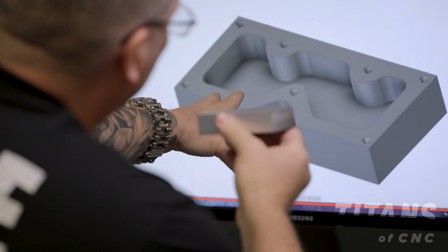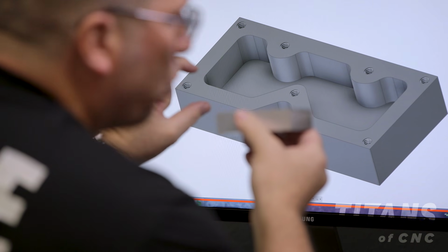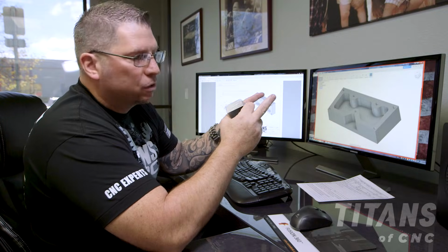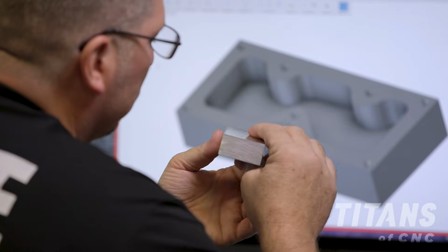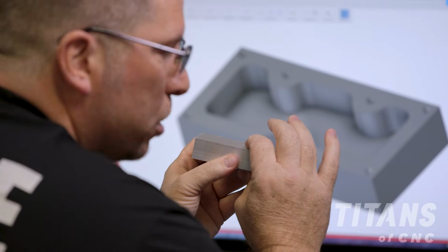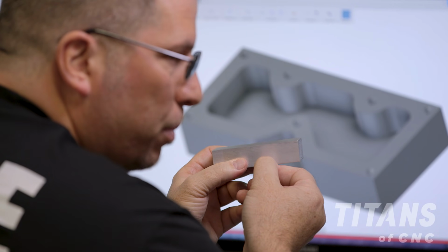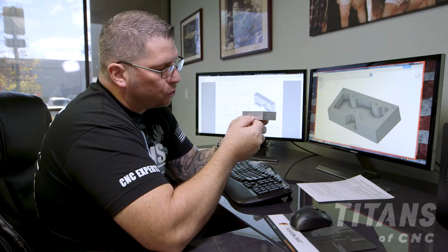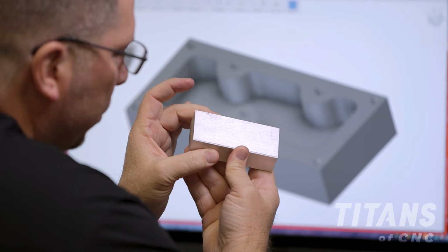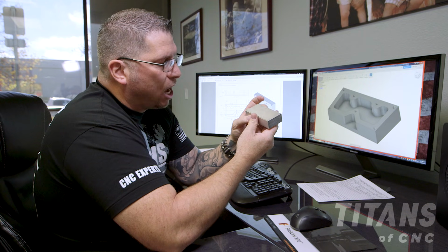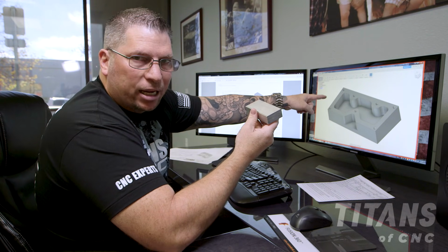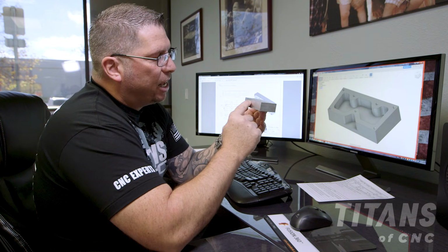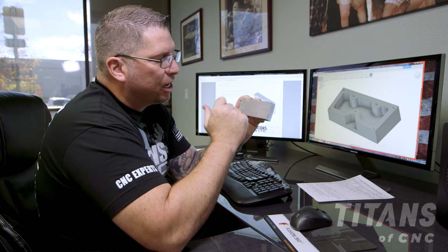We have a finished part that we drew up at 3/4 of an inch by 1.9 by 4 inches. Our finished stock that we called out is 1 inch, so that means there's a 1/4 inch at the bottom because the part is only 3/4 of an inch. Then the stock is the standard rectangle bar. It's 2 inches wide. The part is 1.9, so that's a difference of 100 thousandths. We're going to divide that in half, so we have an excess of 50 thousandths here, 50 thousandths here.